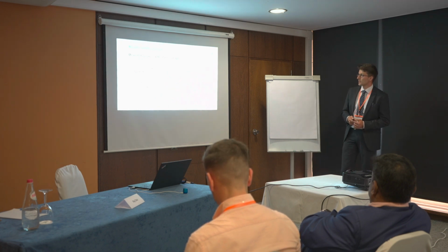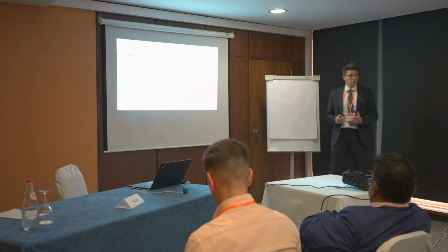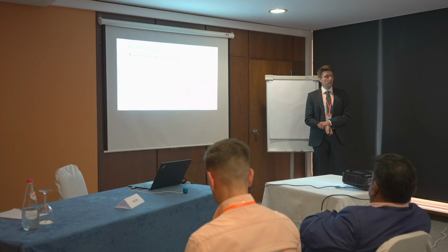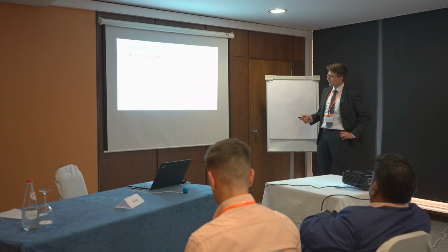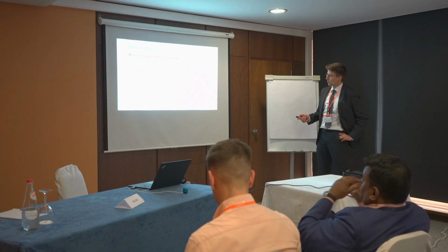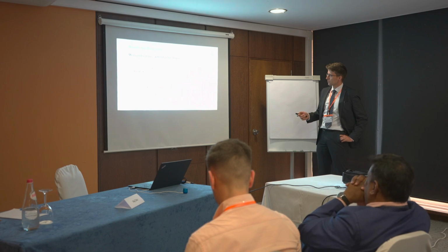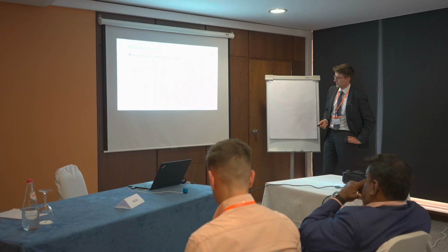So let's go to the results. First, we perform the tests without a specimen and no pulse shaping. That means the incident pulse is quite rectangular. There is no reflected pulse, and the transmitted pulse is also quite rectangular with some dispersion effects.